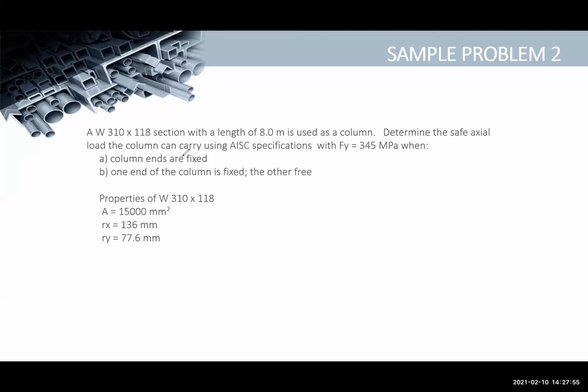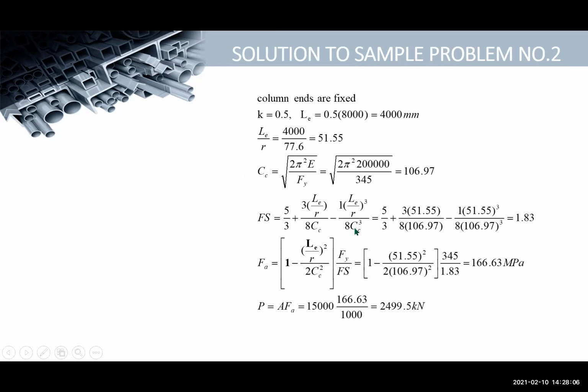So yan, ends are fixed. Yung isa naman, one end is fixed, the other is free. Di ba pag free yung isa, that is 2. Check natin. Ayun, kapag fixed, you notice K is 0.5. So multiply nyo sa L to get your LE.